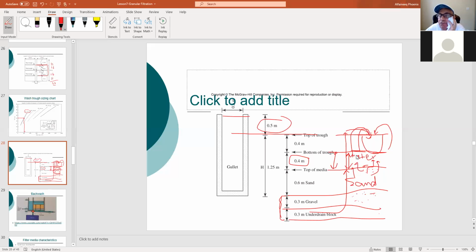So the sand expands to the bottom of the trough. The dirty water is the thing that gets inside the troughs, so it can be removed from there. Now, when you finish, put the filter back to its normal operation, and by gravity, larger particles are going to sit at the bottom, smaller ones at the top. Same thing with the sand: larger to the bottom, smaller, smaller, smaller. In other words, gravity itself is going to take care of your filter. Don't worry about it. It's going to sit back in its normal position.